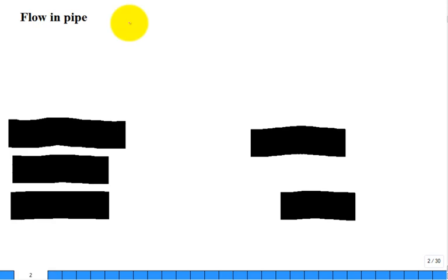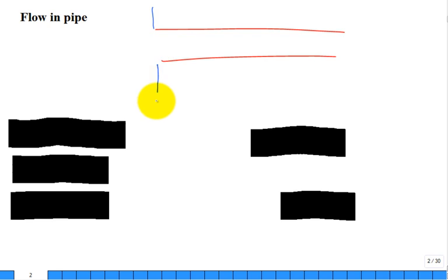So we have a pipe, and often it's important how you get the fluid into the pipe, and it's important as to what's happening. Let's say there's a big tank that's supplying it right here at the corners. And they could be well-rounded, they could be sharp, they could be protruding into the tank, and all that's important for the fluid flow. But let's say they're slightly bell-mouthed like this, so I don't have a big separation region like that. And the flow takes a while. Early on, the flow is flat and then has a sharp gradient.